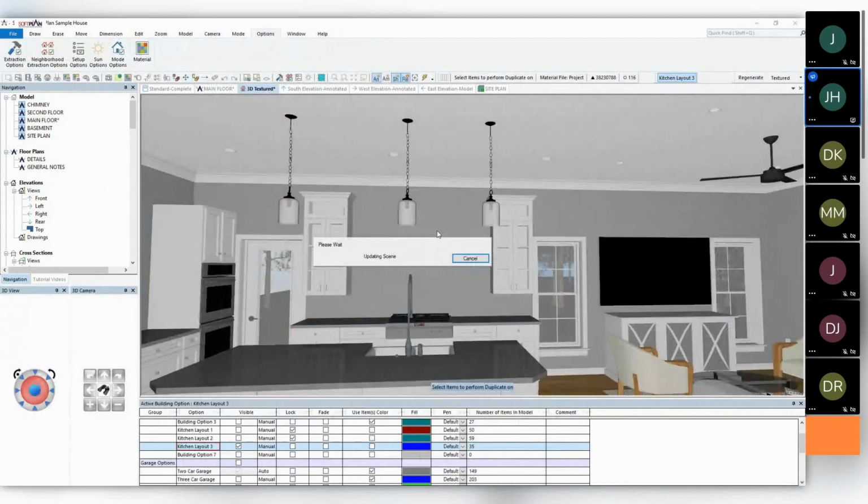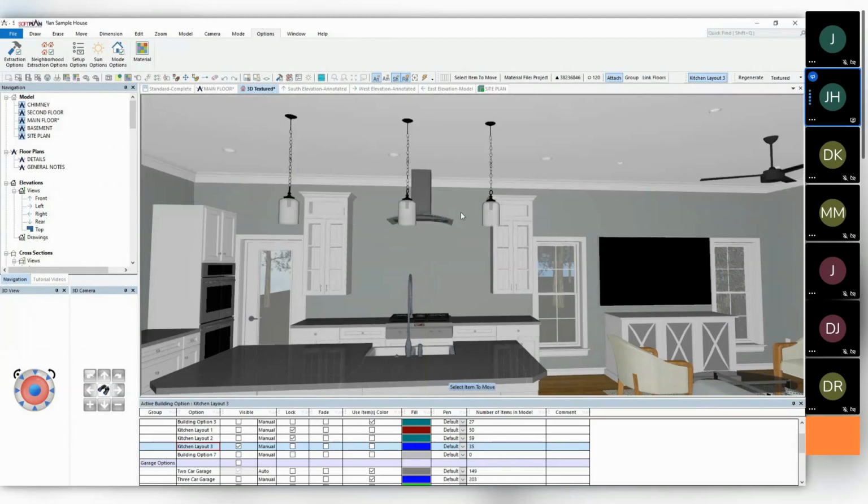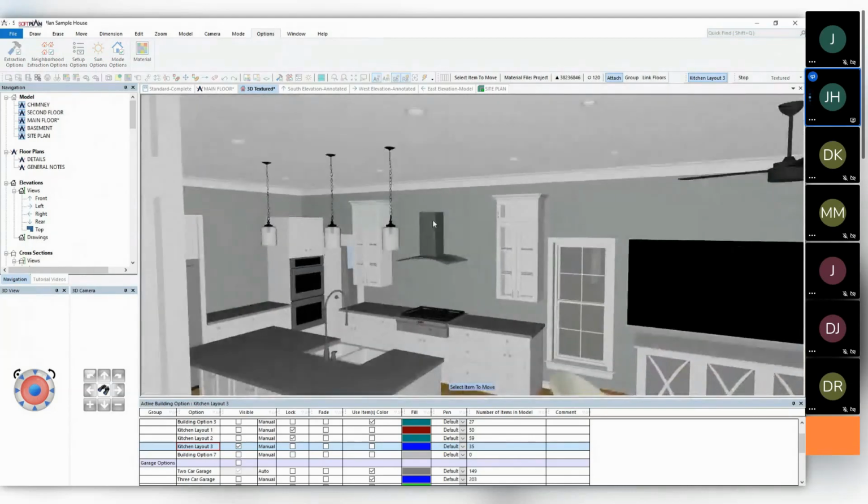All right. And so, I mean, this is us 40 minutes in to the model. So here I'm just going to move this down a little bit, as opposed to, I could have edited. And then using the adjust feature, I'll probably adjust the flue part of this up towards the actual ceiling. And then we'll talk a little bit about modifying the lighting and so on. And so in this case here, using adjust, pick the wall, so I'll just pick adjust and select this and then drag it up, so that it's going all the way to the ceiling, and the crown mold will just butt into it.